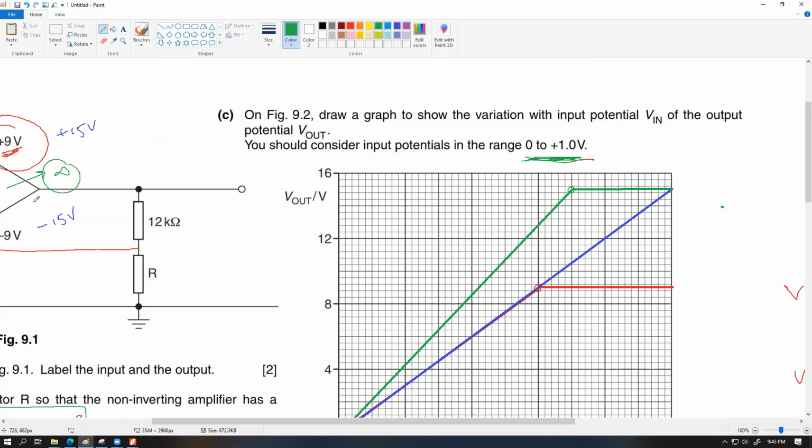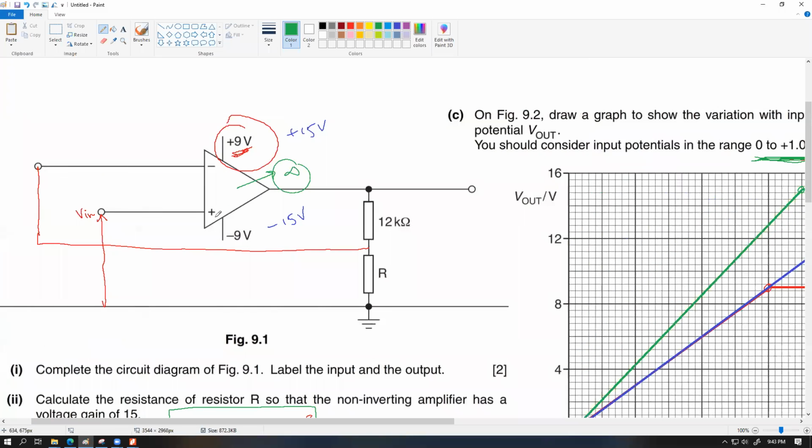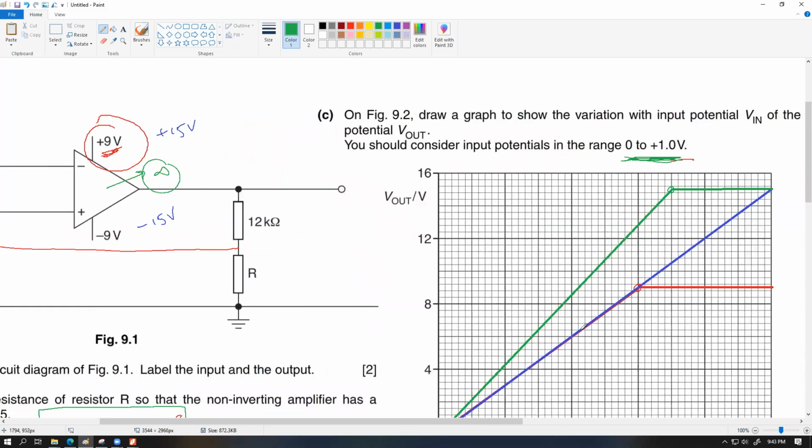So it's dependent on the source voltage. Yeah, exactly. Without this feedback pathway, we do not have that control. Anytime the V plus and V minus have some difference between them, output would always become saturated at the positive maximum or the negative maximum. But if you have the feedback voltage, because of the feedback voltage, you can achieve this proportional increase. It is not giving you full saturation from the very beginning, which Shubhro just asked, which is a pretty nice discussion.